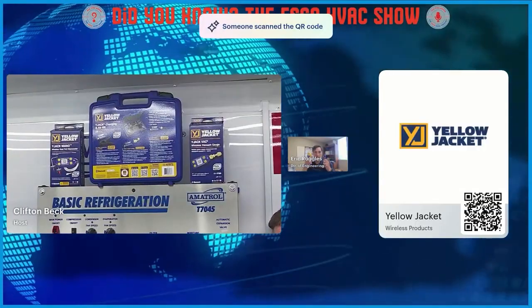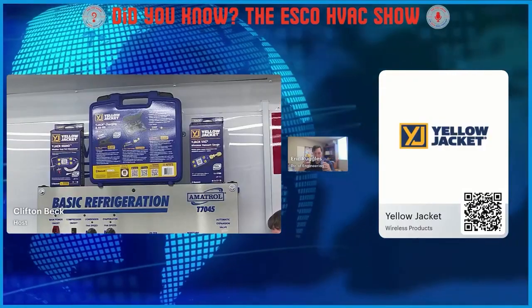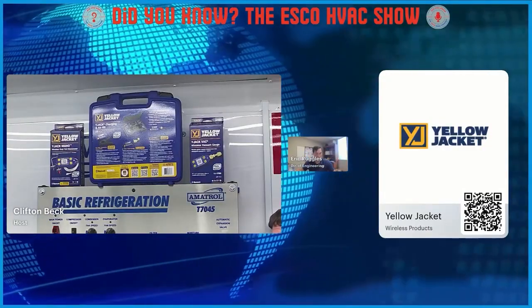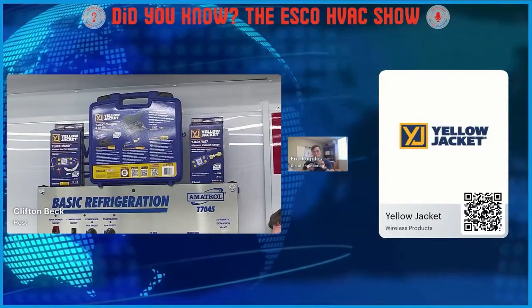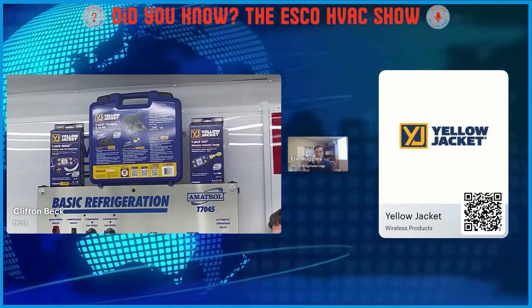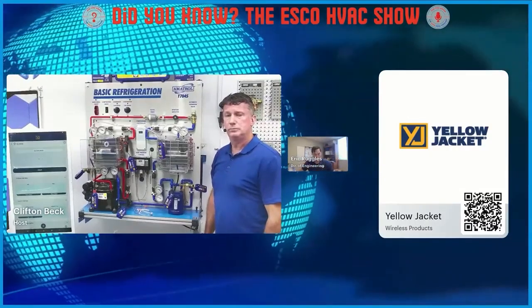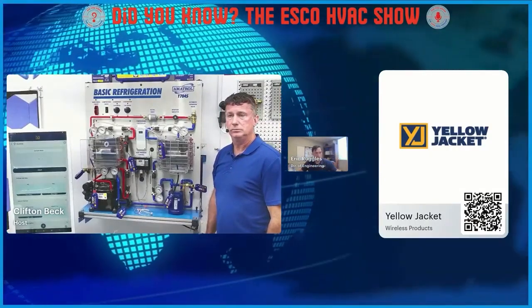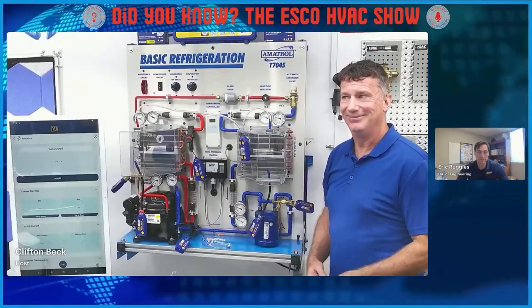But we also have an amp clamp, which is nice for getting your current readings of compressors and fans. We also have an anemometer, so a hot wire anemometer, which you can extend. It actually comes with a magnet, so it can stick to the ductwork as well, so you don't have to hold it in place the whole time, which is really nice. And then you got the bag. So that's pretty much it. Nice. Overall sensors, yeah.